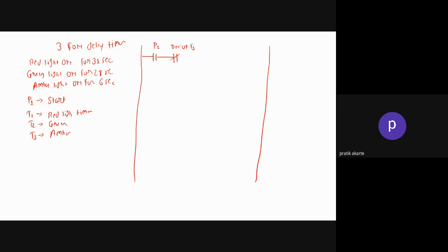So it is an internal relay associated with the done bit of T3. So again I am telling, internal relays are the memory locations which are saved in the memory of the controller, and their activation and deactivation depends on the condition, that is true or false, at the last signal.